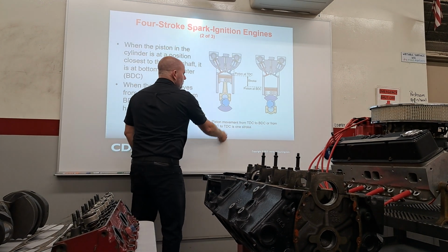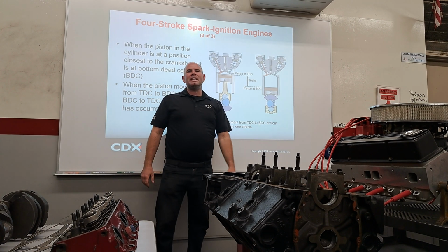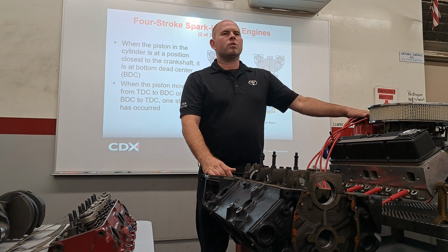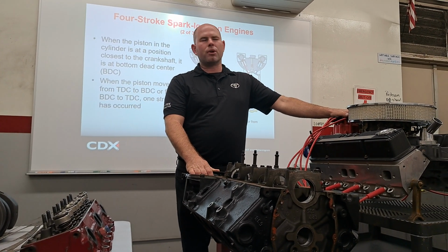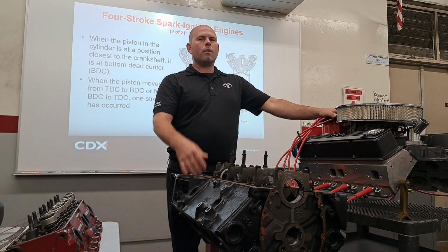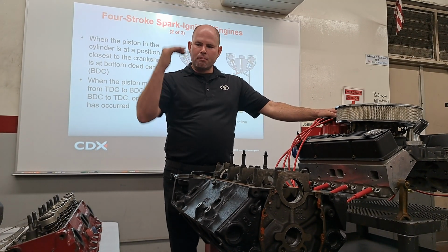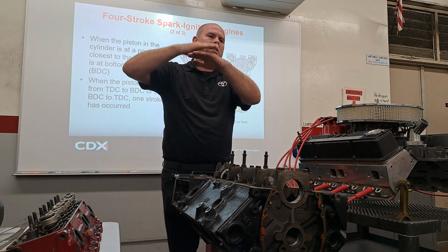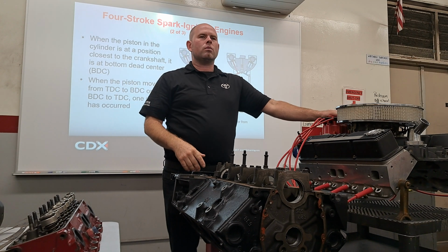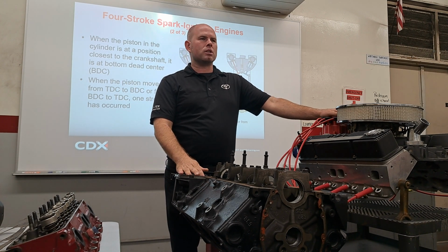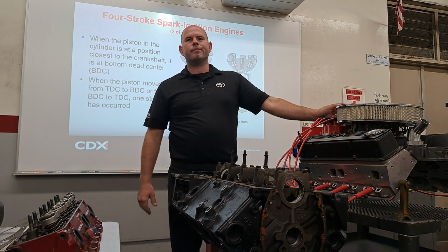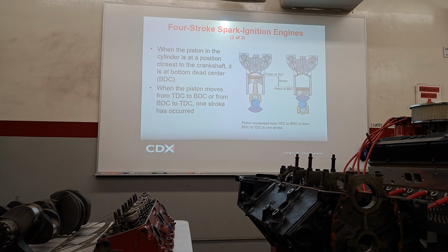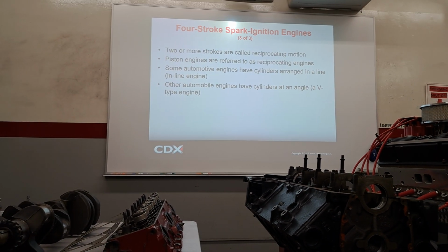Now when you turn it 180 degrees from there, this piston will be at BDC, bottom dead center. We don't generally do anything with bottom dead center. The reason I want to bring it up now is because we're about to talk about compression ratios and stuff. So you need to know BDC to TDC, the movement from measuring BDC to measuring TDC, that's the stroke. So bore and stroke become cylinder displacement. How you measure stroke is that? The bottom to the top. Okay, very good.